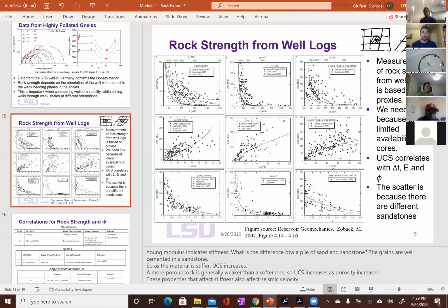That's the Lagrangian description. Whereas the Eulerian would be, say I have a thermometer here and air is moving all over the place, and we still can continue to make measurements at that particular point in space. X, Y, Z never changes, but time is changing. But in the Lagrangian, X, Y, Z is getting updated. And how do we keep track of that changing X, Y, Z in the Lagrangian? The displacement. Remember, it's displacement we solve for in geomechanics. So what's displacement? Well, it's that vector where it is now relative to where it used to be. So this minus that, that's the displacement. And so when you solve for displacement, you are now able to figure out the new material location.